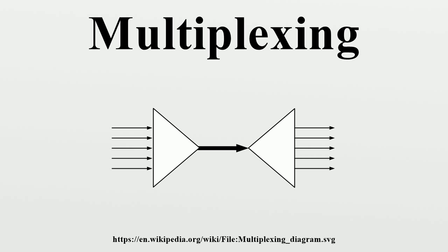This coded transmission typically is accomplished by transmitting a unique time-dependent series of short pulses, which are placed within chip times within the larger bit time. All channels, each with a different code, can be transmitted on the same fiber or radio channel or other medium, and asynchronously demultiplexed.